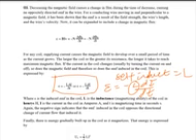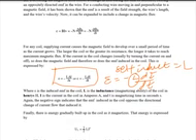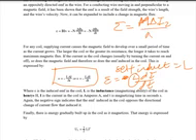The second one is mutual inductance. Mutual inductance is the inductance which is produced by the neighboring coil. Therefore, for mutual inductance, induced EMF is equivalent to minus of what? Let us neglect the minus; the minus indicates the direction. Therefore, mutual inductance times change in I2, which is the neighboring current, divided by change in t. The induced EMF is produced by the neighboring current. The only difference is the current.